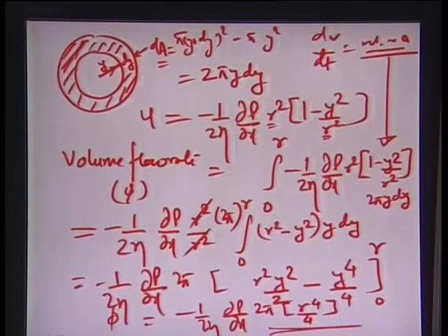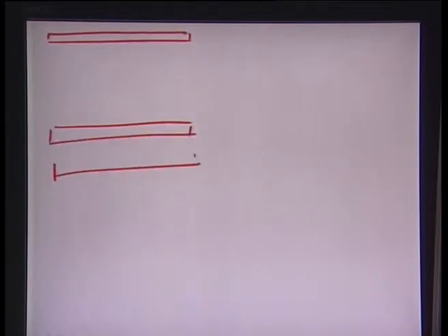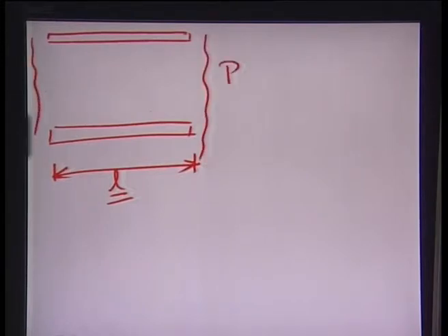If you consider the electroosmotic flow of length L, so essentially you considered the channel of length L, and if you assume that there is a pressure driven flow in this particular example, between the length L and the pressure difference in this case is P, then dP by dx can be represented as P by L.